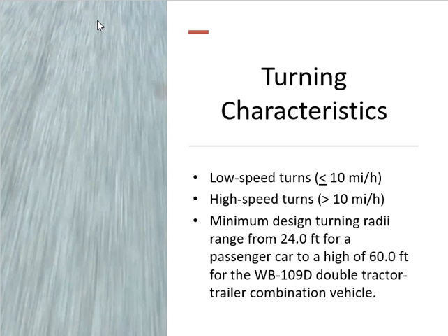Why were we talking about the operating characteristics and engine and so on? Otherwise the engine doesn't have any effect. So we need a bigger engine to accelerate more, because the resistance will also increase. That resistance is more at high speed and less at low speed. In low speed cases, the resistance is almost negligible, almost zero. If you are designing a turn for low speeds, this value is even less than 20 kilometers per hour.